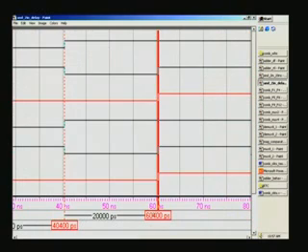You can see one more cursor here, and the actual cursor is right here, and once again there is a marking here. It marks the interval between this cursor and this cursor. That is how we can find out the rise time and fall time of the wave, and so on, if there is ringing. But it will reflect only after back annotation, and not at this stage.